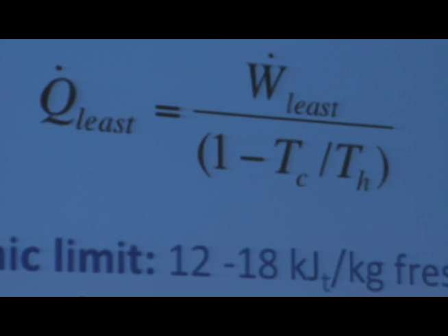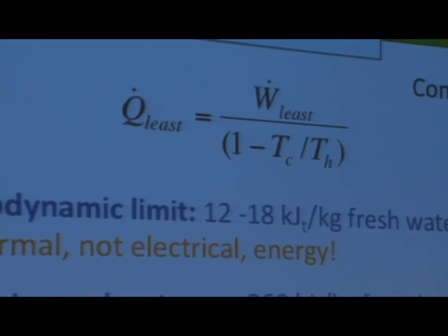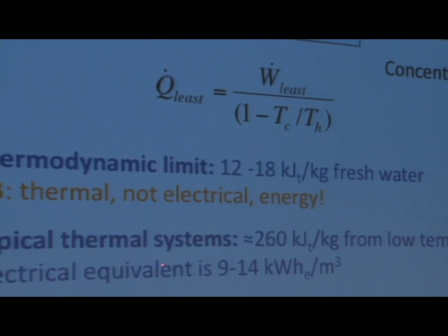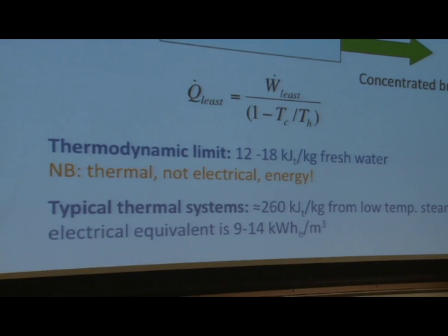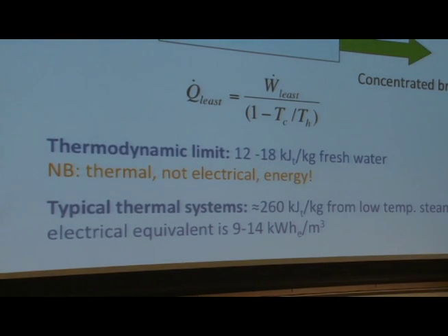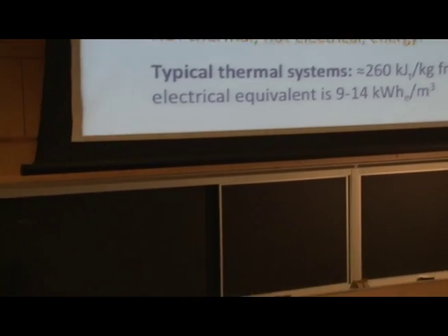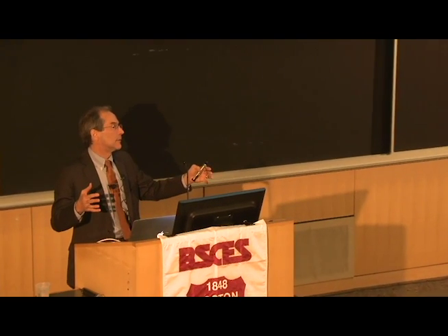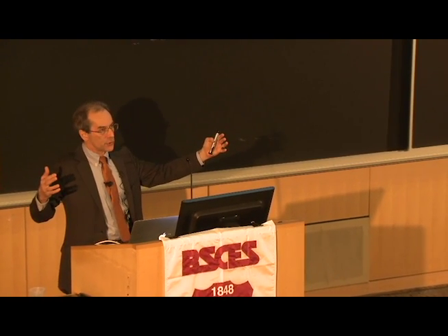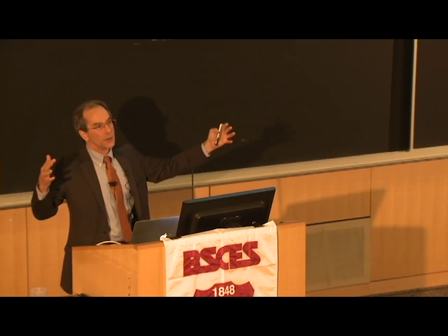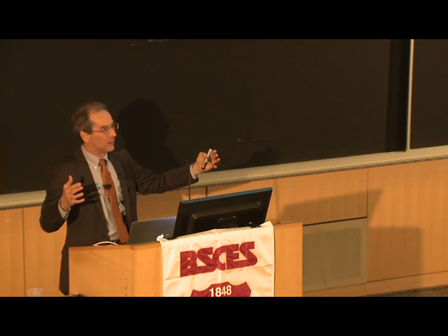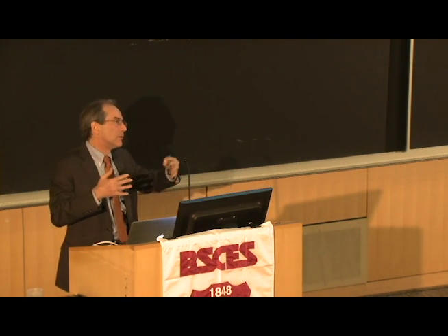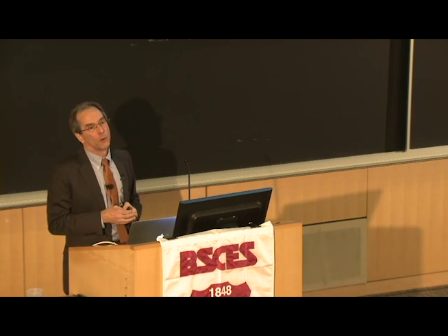Now, a real system, such as the one I showed you in the picture before, requires about 20 times that much thermal energy. It's a long way from the reversible case, very long way. There are a number of reasons for this. One is that the top temperature tends to be very low. Another is that to get reversible performance, or anything like it, I would need very large heat transfer surfaces. That means very large condensers with very large amounts of expensive copper-nickel alloy piping. It would not be economical to build this system strictly for energetic performance.